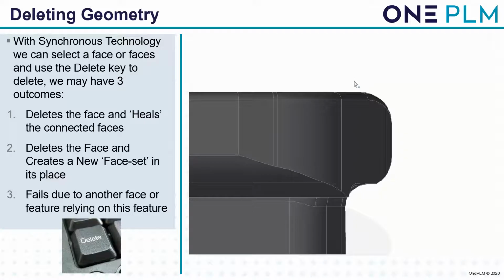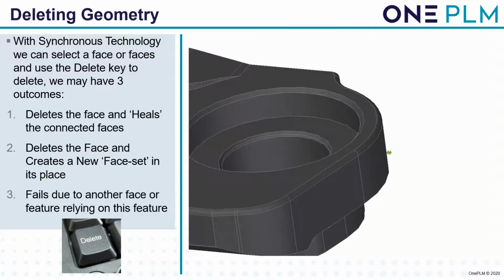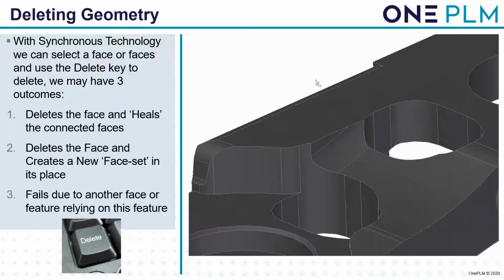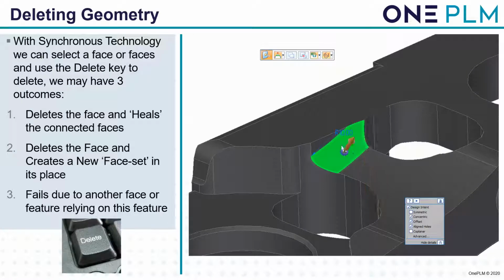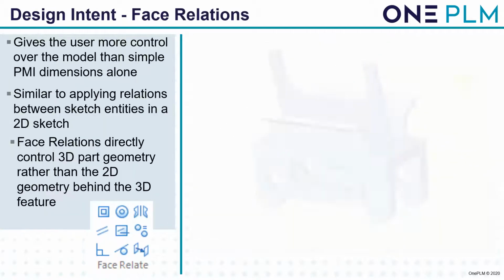On these, it's quite easy to fence select the entire area and then delete, and we can see that has now correctly deleted all those. And then back to the first one, very simple one. This is going to recreate, extend those faces to where that needs to be on there.